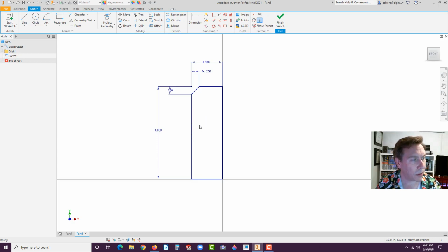Now we're going to go ahead and we're going to put like a little radius here, a circle. So go to the circle tool and locate yourself right about here. Notice I'm inferring to the 0.25 top edge of the chamfer. And right in the middle, your Y should be about 1.7-ish. Click, drag it out, and make it 1 inch. And now let's go to dimension and dimension the center position of that to the bottom edge. Drag your dimension to the left and make it 1.75.